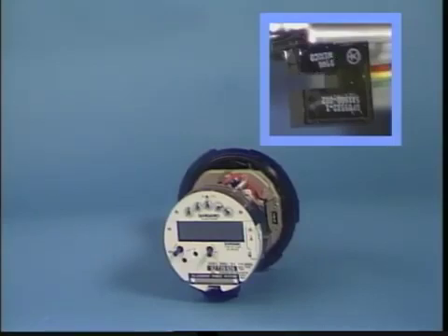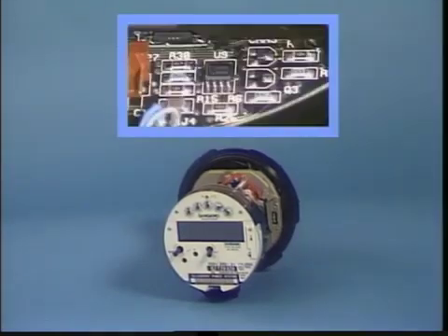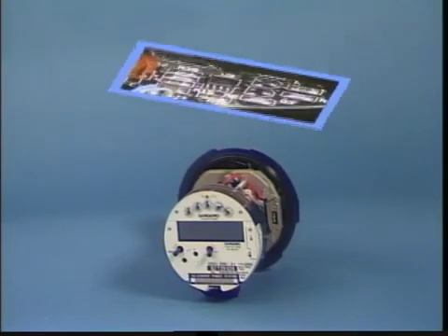The two parts of the photo-optic assembly fit above and below a vane, or shutter, that is mounted on the meter's disk shaft. As the shutter rotates with the meter disk shaft, the shutter intermittently interrupts the light path between the diode and the photocell. This generates pulses that are counted and stored by the microprocessor. The faster the meter disk and shutter turn, the more pulses are generated, counted, and stored during the demand interval.